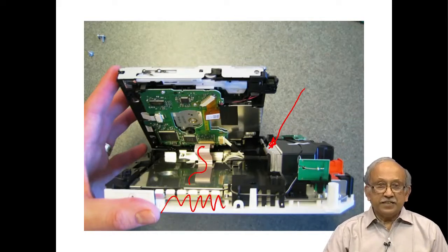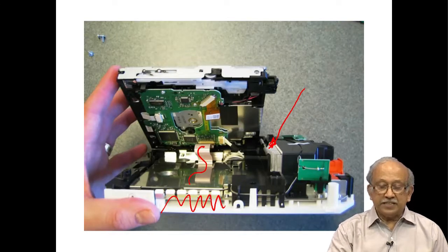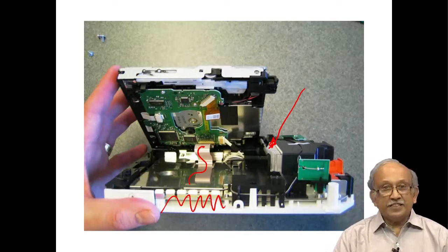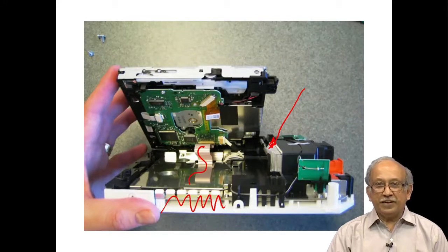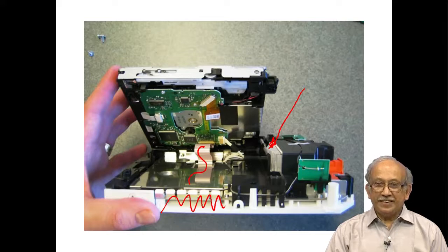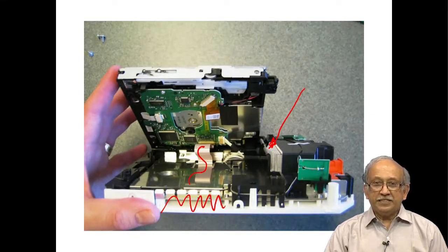What this heat spreader does is it will take heat from any of the hot points, and then try to take it to another place. One interesting thing you will notice is it is not black color. Heat sinks need not be black. In fact, they have found out that heat sinks probably should not be black, because black is a very good radiator as well as it will even absorb heat. It depends on the temperature difference.